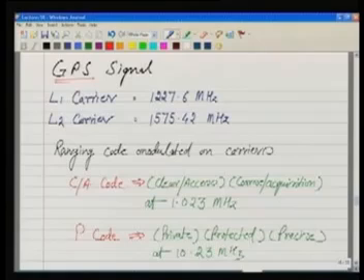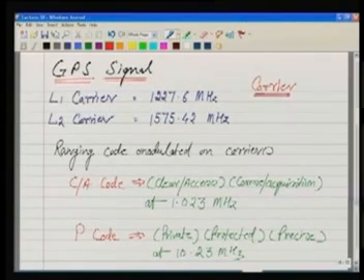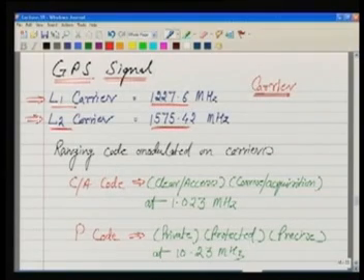Okay. Next thing about the GPS signal, because so far we are saying radio waves and carrier. Basically, we have two bands which are being used as the carrier here. Now, what does two bands mean? One band is working at this frequency and the other band is working at this frequency. We say them as L1 and L2, and they are carriers. Now, why are these two used? Why not one? It helps, as we may see later on, in eliminating the ionospheric error.